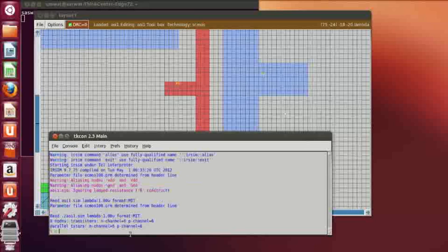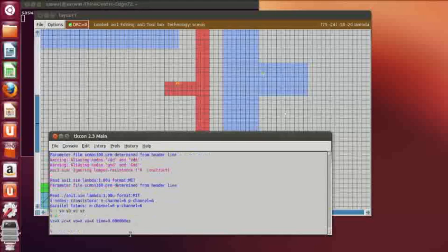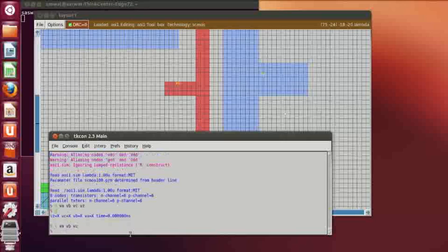Then W, that is watch, there are three inputs, VA, VB, VC, and the output is VZ. Then display, so all are X. Then what will I give as the combination? Okay, let me give low to all three, VA, VB, and VC. What will the output be?